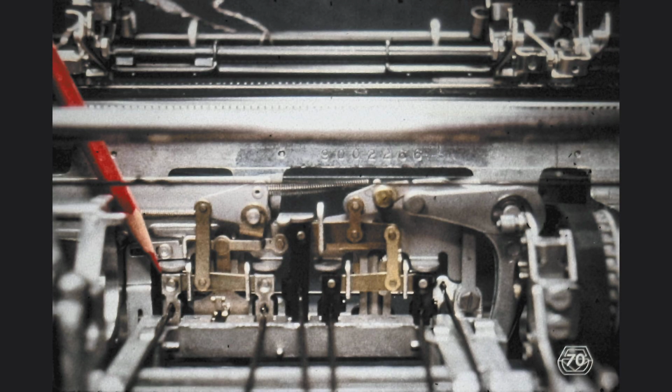Now cycle the same character T one more time and observe that the tilt 2 latch, indicated by the red pencil, remains in its rest position against the stop pad. It becomes obvious that the lever which connects the 2 latches uses the point indicated by the red pencil as the pivot point for this operation. We again summarize our observations by stating that using the tilt 1 latch only, the one on the right side, reduces the total amount of input motion to 1/3, so that only 1/3 of the vertical motion obtained from the positive latch bail through the tilt 1 latch is transferred into the tilt tape system.